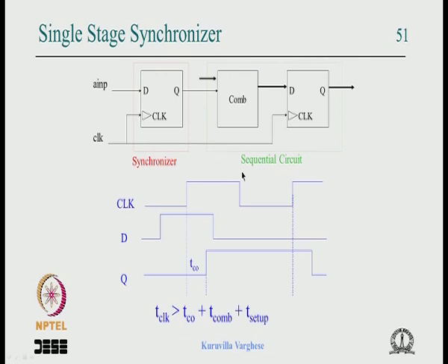But fine, I mean that sounds great, really great. Once again a clever student will ask a question: is the problem solved? Now we said that this is changing with no relation to the clock, and that comes here and upsets the destination flip flop, causing metastability here. But now we have the same issue here.